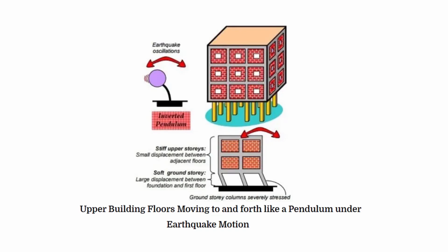The collapse showed that the buildings had many vertical irregularities like soft stories and weak stories, especially on the ground floor where there were large openings. So the construction authorities must be very strict in checking the building's horizontal and vertical irregularities, and they must ensure that the design conforms to the local seismic code.